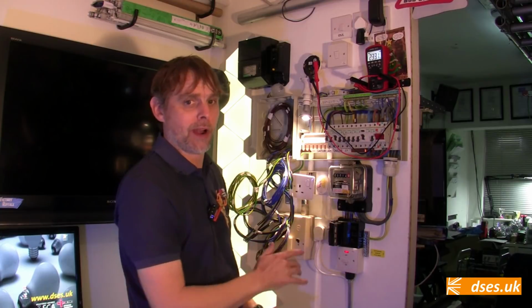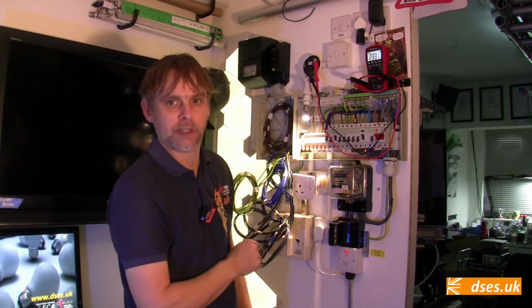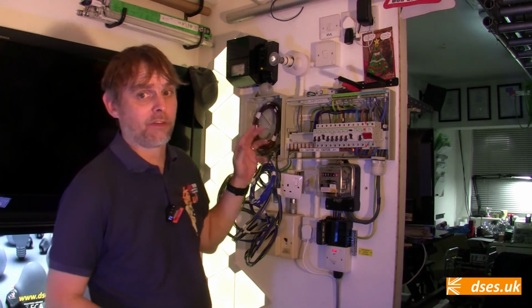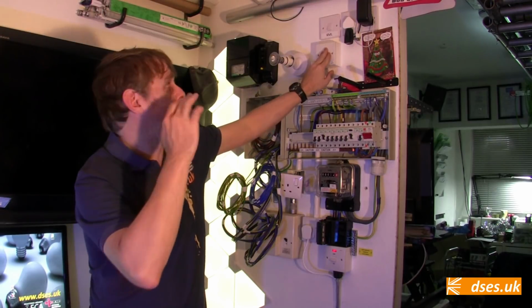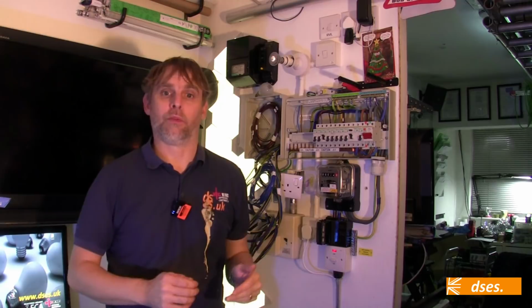Because neutral and earth are grounded, stray capacitive currents get squashed and can't leach into neighbouring wires or loads if line, neutral and the circuit protective conductor are grouped together throughout their run. One thing about my test rig, which will probably differ from what you're seeing at home though: if I turn my light switch off, then my nuisance glow problem goes away. For most people, turning the light switch off is when the problem shows up.